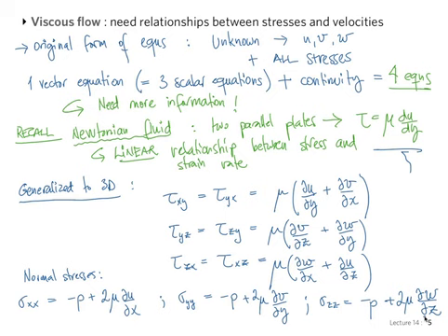Yes. So is that a differential or a 2 for the mu? It's a 2 mu. Okay. 2 mu in all cases. 2 mu and du dx. So the component of compression in the x direction. Basically, if you imagine, the viscosity of the fluid resists all motion. So if I compress the fluid, there's also a resistance due to the viscosity there.